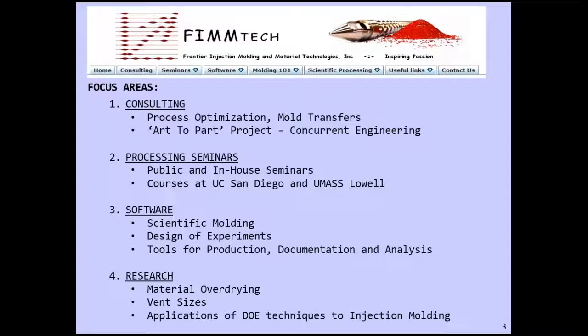I was just at one of the facilities here in northern United States, where they built a huge mold. It runs on about a 2,000-ton molding machine, and they have realized there's an issue with the way the part is designed. There's a thick section on one side and a thin section on the other, and they want the part to be perfectly flat. It's too late to change any of these things.